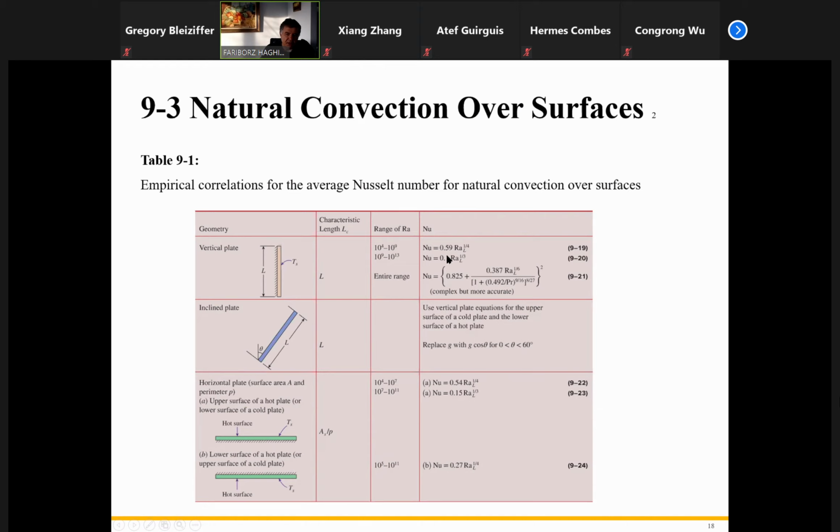The problem with convection is most of the work has been done experimentally. Therefore, sometimes the error can be 10%, 20%, 30%, and so on. It is not based on solving the differential equation. They carry out experiments with different types of gas, different sizes, and different temperature differences, and they find different values and put them on a curve.